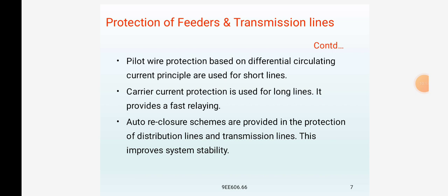With this arrangement, every fault that might occur must involve a connection between a conductor and an earthed metal part. Frame leakage protection is normally applied to small sized metal clad switchgear units.